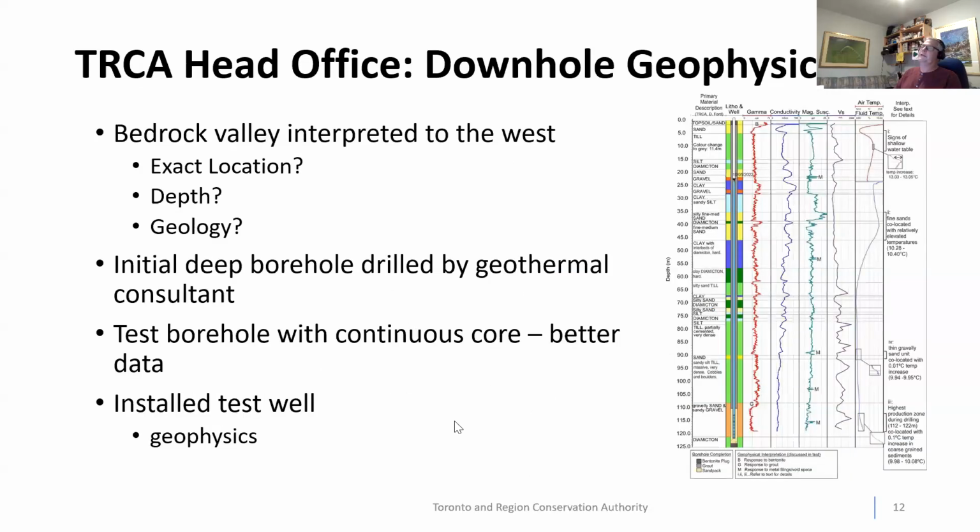We also use downhole geophysics, and this was from a well at head office. It can help refine some of the information that you have from drilling. You don't always get 100% recovery. So going back with geophysics, we can look at sediment properties, and even porosity and permeability can be estimated now with some of the new tools. And every year it seems the tools get better and better and smaller, and they're able to put a lot of their tools down a 2.5-inch well now, which opens it up to a lot of the wells installed by the consulting community.